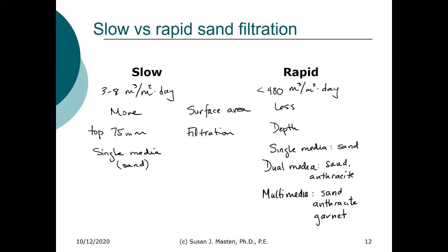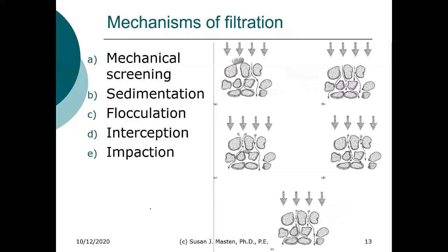We can also have a top media, above the sand, of activated carbon, where we're not looking at filtration, but we're really looking at an adsorption of soluble material. And we'll talk about that when we talk about adsorption.